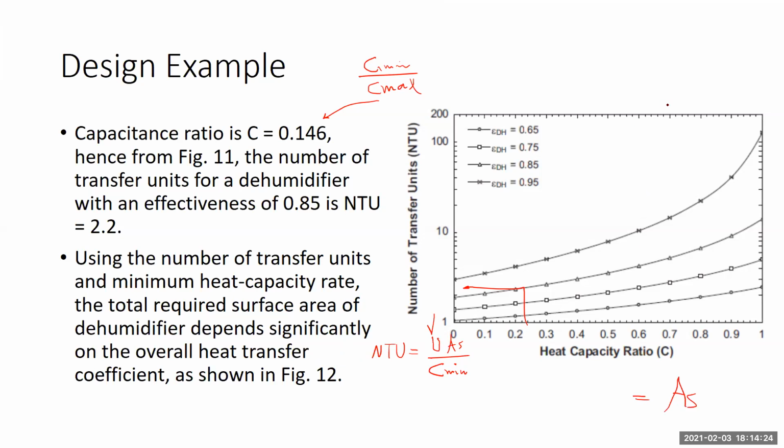If you are going to have tubes, knowing the diameter of the tube and the length of the tubes can determine how much length of coil is needed here. So the surface area that you calculated from this formula is going to equal pi d l. If you have a large number of tubes, it will be n times pi d l, where L is the length of the tube and n is the number of tubes.